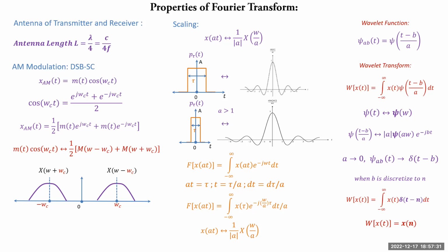And this is a very important step in understanding the wavelet transform, which says that whenever a signal is observed using the wavelet transform at the highest time resolution, that is, whenever the wavelet function becomes very, very small in the time domain, it is equivalent to a sampled version of the analog signal. And that is a good starting point in understanding the wavelet function. We'll have one more lecture on the wavelet transform in our subsequent lecture.